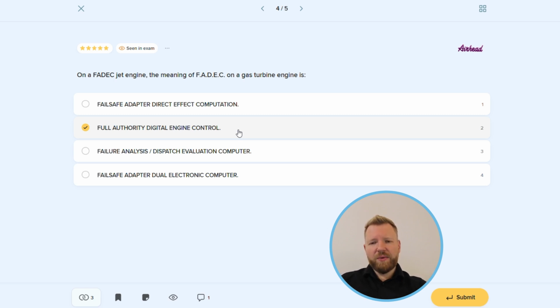EEC consists of two separate channels, so two separate computers that sense a variety of data from engine itself, but also sense a thrust lever angle, so the power requested by the pilot. The system itself has many features, from sending commands to FMU in order to deliver appropriate amount of fuel to the engine, commanding bleed valve's position, variable inlet guide vanes or the stator vanes position, up to responding to the engine master switches or incorporating engine protections.